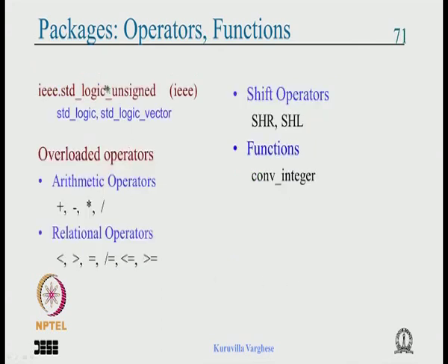That is specified in another package, std_logic_unsigned. It works with std_logic and std_logic_vector, and you have arithmetic operators plus, minus, multiplication and division, and relational operators like less than, greater than, equal to, not equal to, less than or equal to and greater than or equal to.